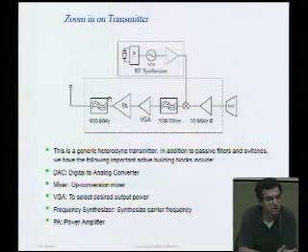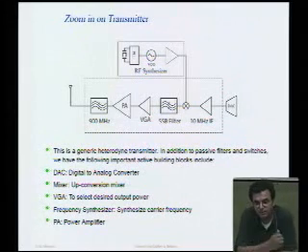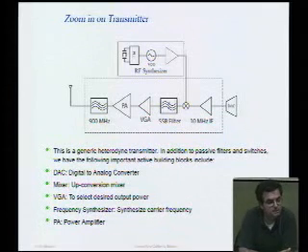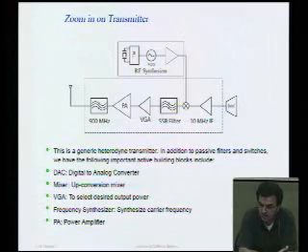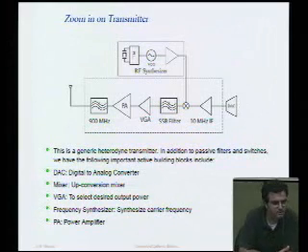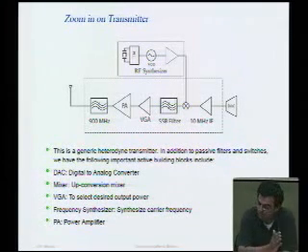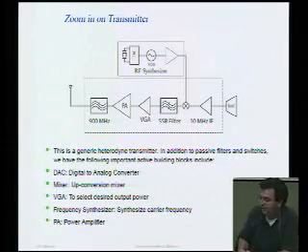It's actually quite shocking. A lot of times you go out there in industry and you find people building things that are power drivers and they're using linear circuit techniques, and you find the efficiency is actually pretty dismal, a couple percent at best. In this class, we're going to learn to build power amplifiers that have theoretical efficiencies that approach 100%. Practical efficiency is always a different matter, but at least 50% we'll see.